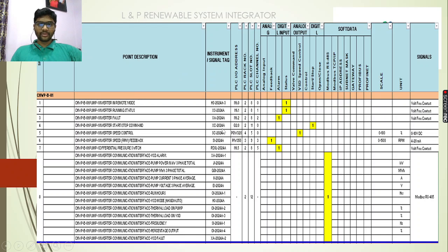So if we get into the hardware signals: remote status, run status, fault signal, start, stop, speed control, and speed feedback, differential pressure switch. All these things we need to monitor. And also we can communicate through Modbus RS485, and we can get the soft signals from the VFDs.